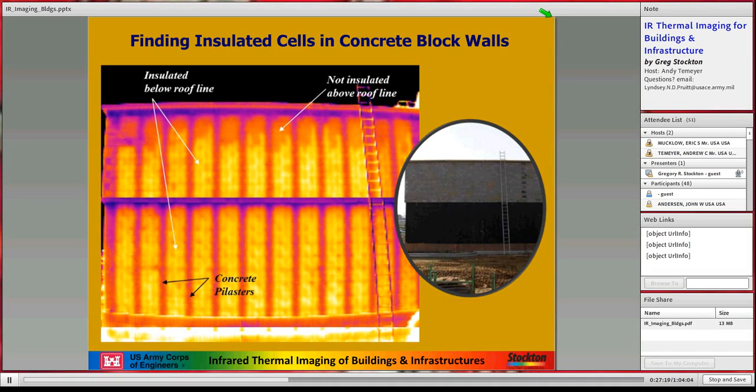about 2 or 3 hours after sunlight or sunset, you can see the concrete that is the solid grouted areas. This is a great quality control for a construction site. You can't see the rebar, but you can see the grouted cells.